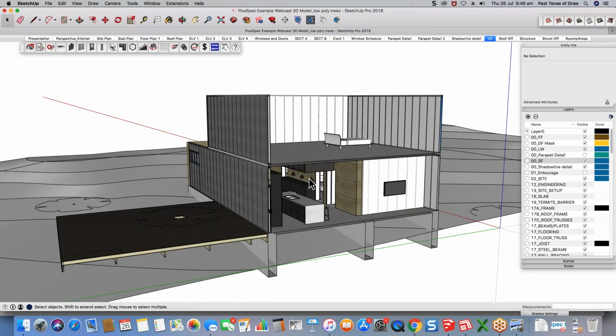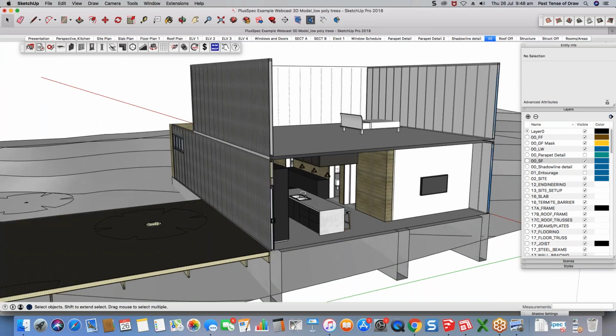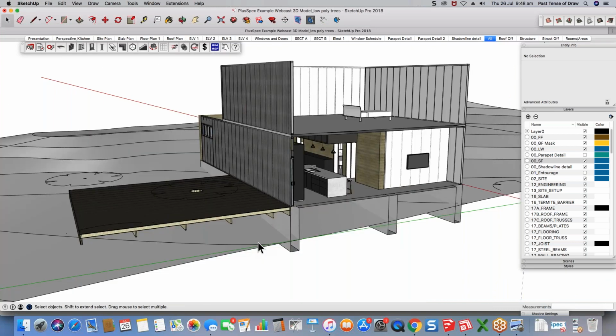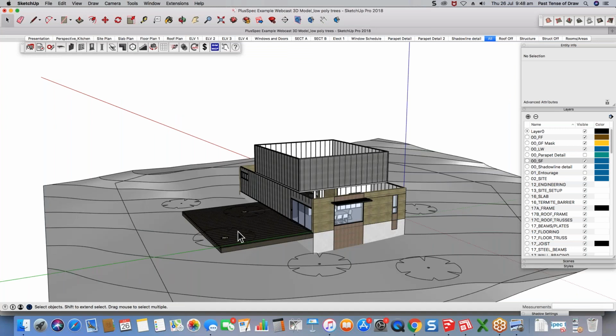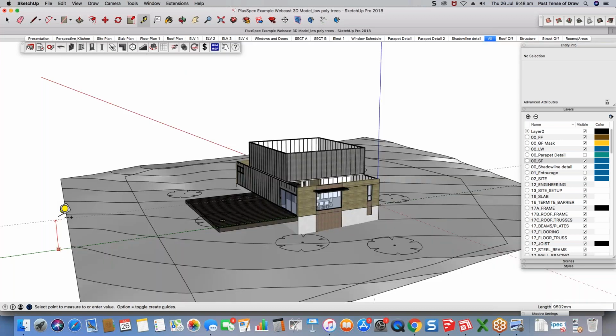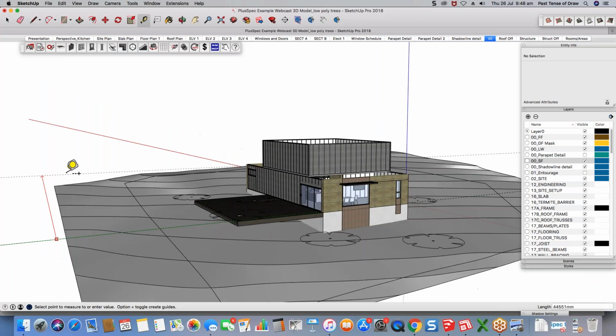If you're talking about the grid though, I have to do it from scratch, but if I was to place a grid, I just go back into all and say, okay, I want to set on my blue, and that's the top of that floor. And then I want to grab it and put it on top of my slab, making sure that you're on the blue. That's the only thing you need to really ensure. And then that's the top of that slab.